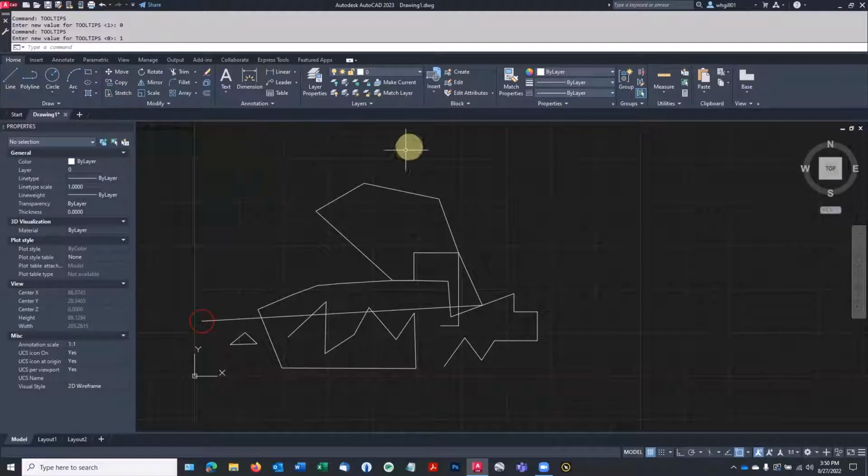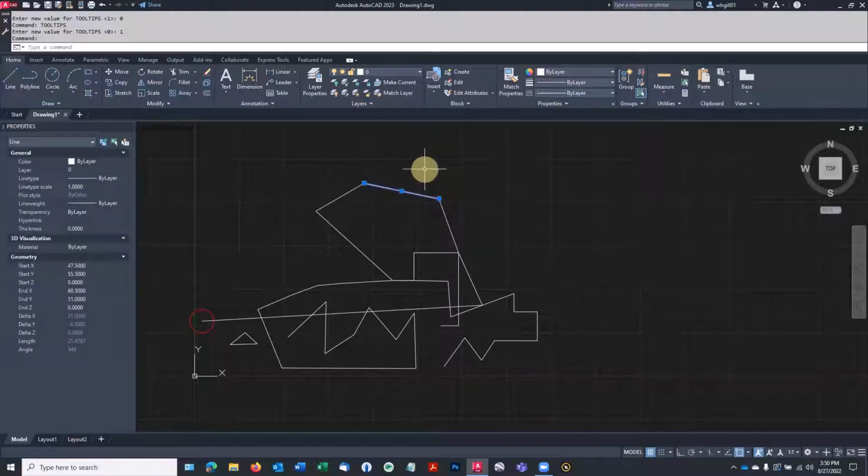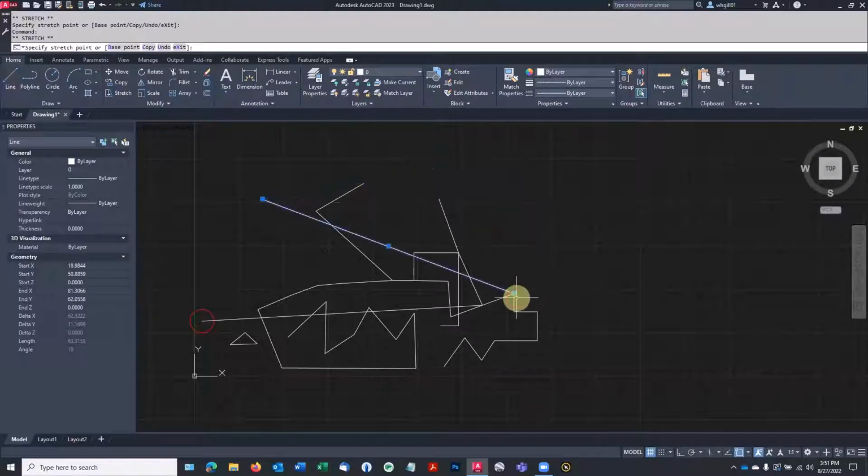Once you've made some objects like these, there are a number of ways to edit them. One is simply to select them, and then each has a number of grips. There's always one that moves the object itself. And then there's others, in the case of lines, at the ends, where you can then move their endpoints.